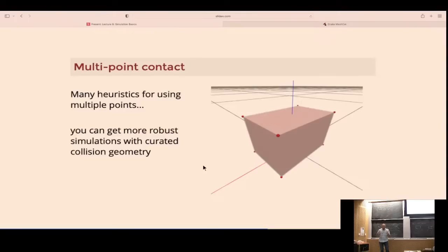is that we often put extra contact geometries down. So for that red brick to fall and land in the piles and be accurate in all the different cases, if you visualize the collision geometry instead of the visual geometry, you'll see that the red box has a little box just partly inset from the original box, and then there are zero radius spheres at all of the corners.